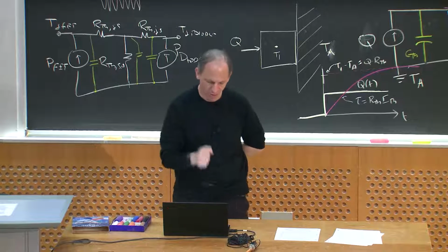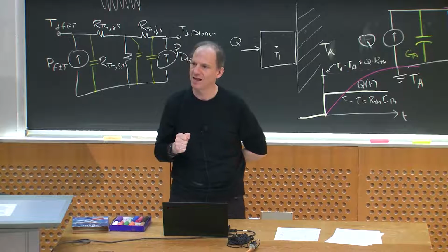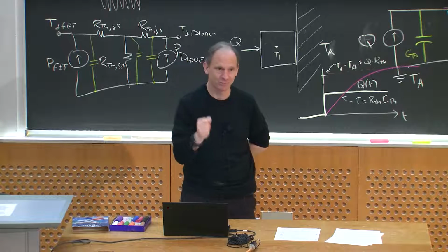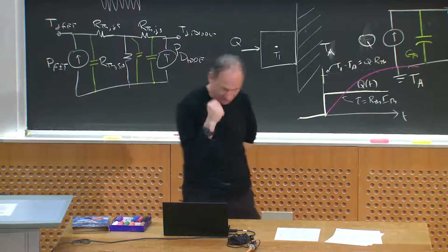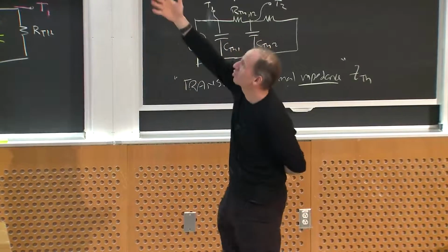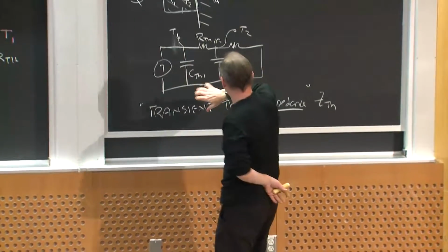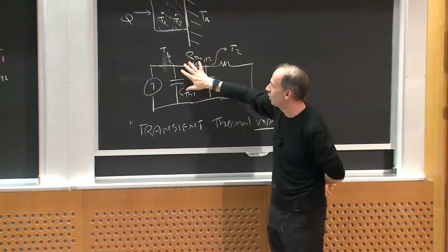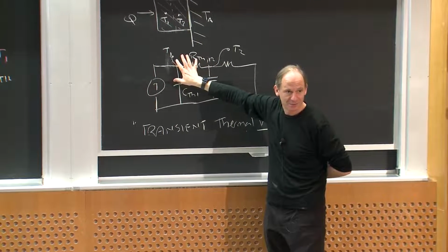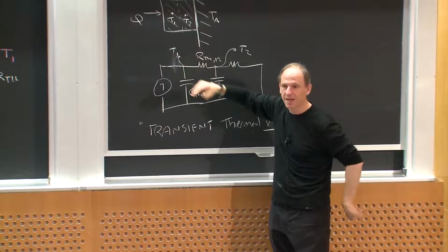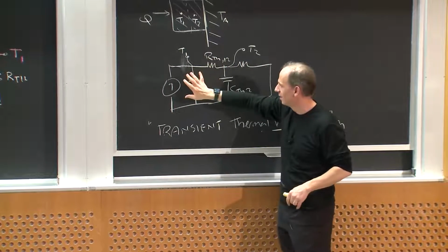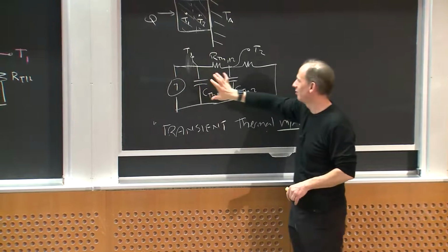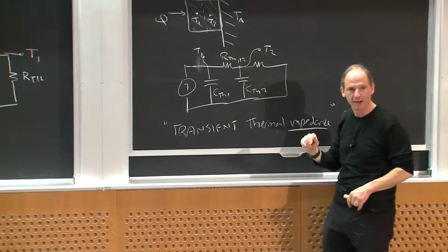Okay? So transient thermal impedance is a step response plotted on a log-log plot. The other thing I should tell you is that you could somehow extract that model and come up with a thermal model for the device. Maybe it's only 1 RC that you approximate it with. But in a complicated big module, it might be a more complicated model because there might be like the thermal capacitance of the silicon, the thermal capacitance of the header, and so forth, right?